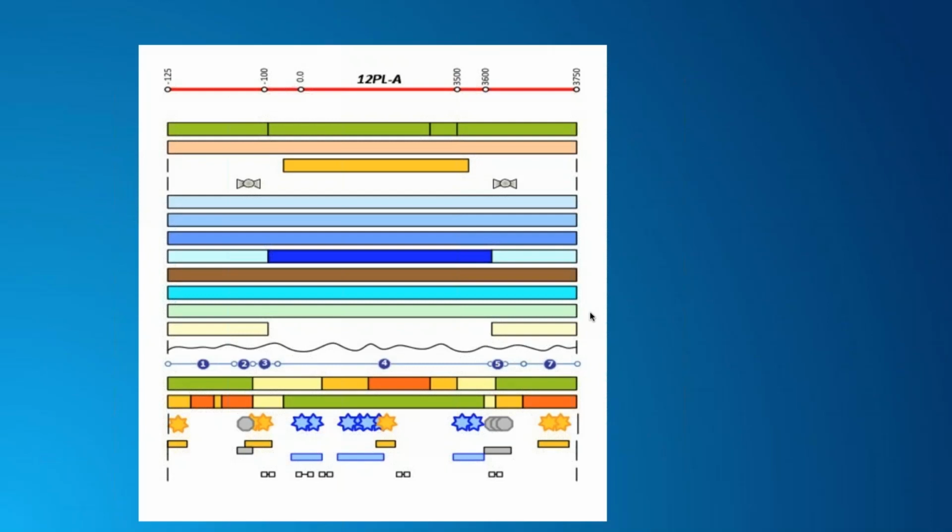So I split up my data elements, say my pipe, my coating, my valves, all the things that I have. And instead of breaking that GIS pipeline down into a million different pieces, I model that data in its individual components on top as linear or point ranged events.